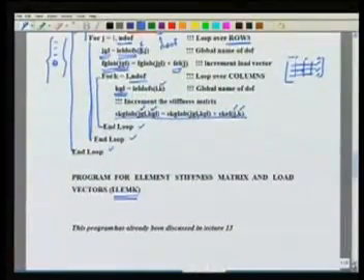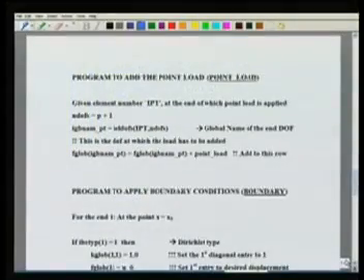For this we needed the element calculations, which come in here. Those element calculations will be provided by our routine LMK, which we had already discussed in the 13th lecture. So now, after we have assembled the local element stiffness and load vector entries into the global stiffness and the global load vector entries, what are we left with?